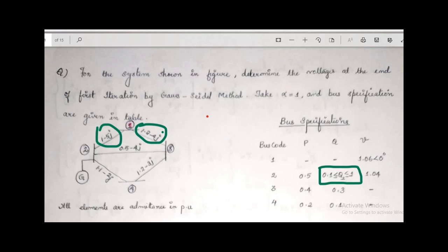You should be very careful while calculating, starting from the Y bus. Step 1 is Y bus calculation. For each step, from the valuation point of view, there will be points. So even if you don't know how to solve it, at least solve the first step, that is the calculation of Y bus. The second step is also quite easy, initialization of bus voltage. Now, if all the buses are load buses, there is no issue with the question. You can directly solve it. It is very simple.